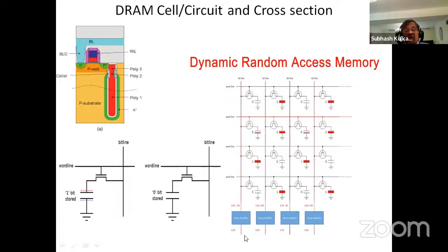Through a sense amplifier, you can detect that. Here, this doesn't change because this is already charged. So between this bit line and that bit line, there is a voltage difference, which is detected. So you can tell which is 0, which is 1, or which is turned on and off. And you can write the cell as well. So that hopefully gives you some feel for how these transistors are used as switches.